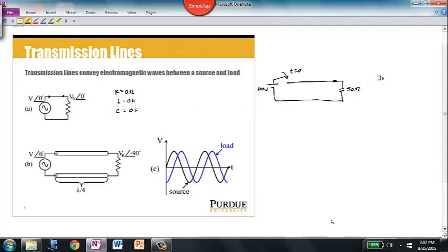What conventional circuit analysis would tell us is that I is equal to the voltage divided by R, and that's just 100 volts divided by 50 ohms equals 2 amps. So we've got some length of wire, and conventional circuit analysis would lead us to believe that 2 amps appears instantaneously in the entire circuit because of the drop of 100 volts across the 50 ohm resistor.